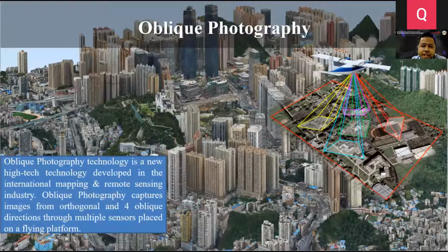They have 5 camera lenses and it's commonly used. There are many sensors that simultaneously collect images from different angles. Images captured from vertical to the ground are called positive films, and images captured from a certain angle between lens and ground are called oblique films.